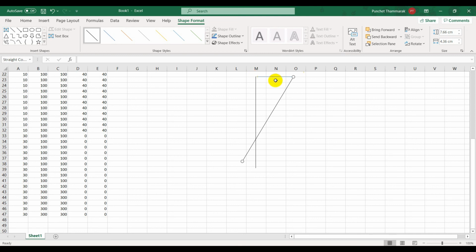For example, 0 strain in concrete and 7,000 microstrain compressive strain in concrete, because 0.002 times K, which is 2000 K microstrain, corresponds to f'c. So if the concrete is ductile due to the confining effect, you'll be able to go further and further. I think 7,000 microstrain is quite a lot already for concrete, so it is not likely.